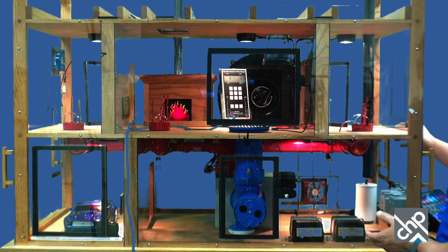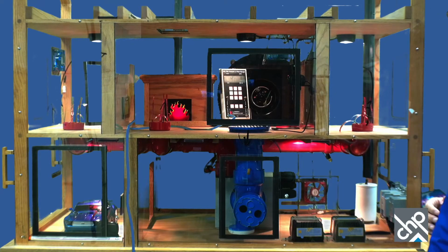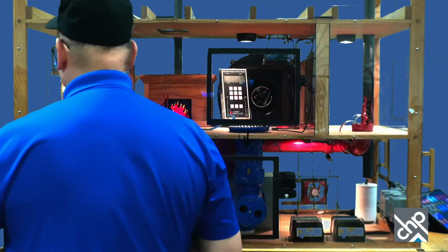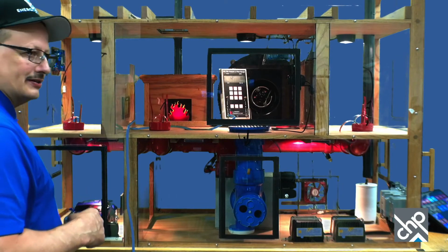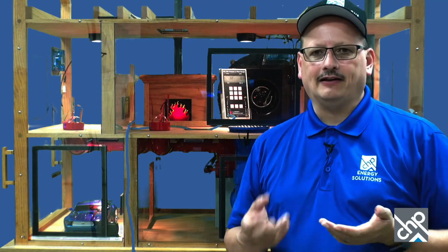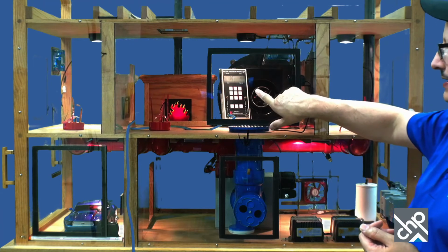So as you can see now, the smoke's going out the chimney, and I'm going to close the door just like I had done before, but this time I got the smoke going out the chimney. You see, it pretty much has slowed it down, started bringing it back in, even just from that one door. But then when I close the second door, again, remember this is a little model, so it doesn't take much to backdraft it. So right now you see the smoke's coming in, and we're at a -4 Pascal.